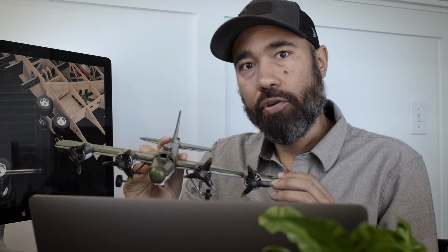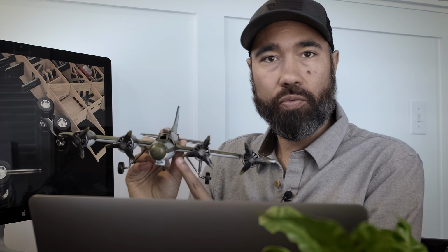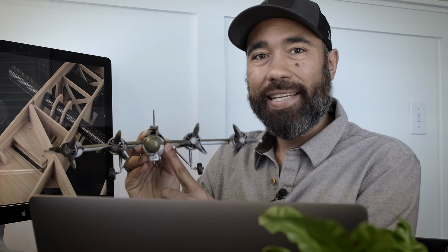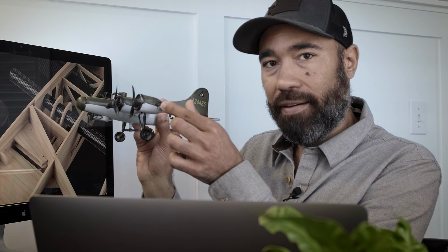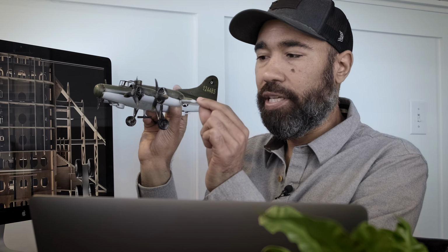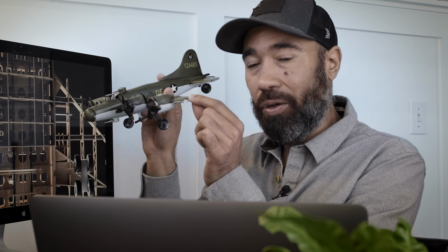So I've got my handy dandy super scaled model airplane here to give you guys an idea of what the washout is for. If you remember when I started with the root airfoil, what I did was I actually angled it ever so slightly higher. So the angle of incidence was a little bit higher. Whereas when I did the wingtip, I actually did it tilted down.